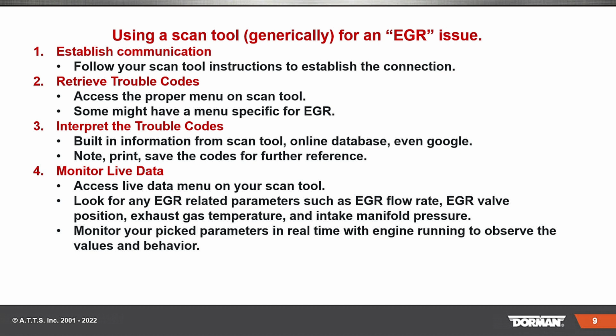But anyway, establish communication, follow your scan tool instructions. You know what your scan tool does and what it can't do. The rest of it is, let's start with retrieving the trouble codes. Depending on your scan tool, access the proper menu on the scan tool. You might have something that's very specific just for EGR, with the bells and whistles for it.